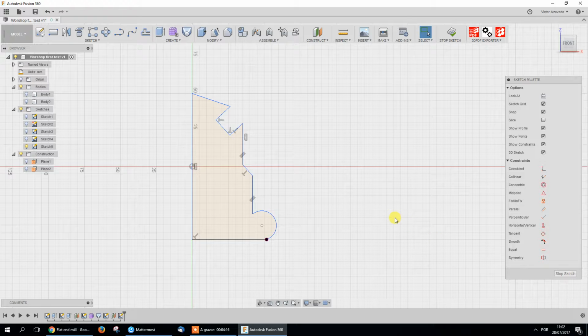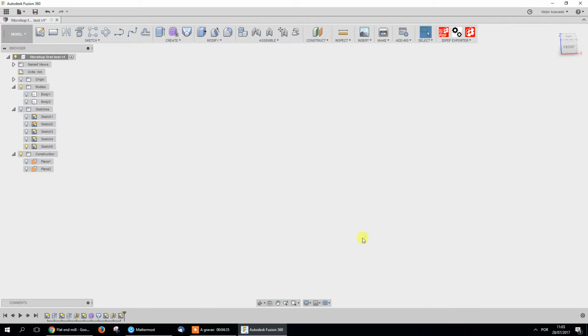I've noticed you had trouble changing perspective and going to the planes. Your problem is if you're inside the sketch, you can't enter the others. So you need to stop the sketch. And it's not showing. Okay. Stop the sketch, and then you can double click and go to another feature. Okay. So in this case, I wasn't able to delete that. So it changed perspective.